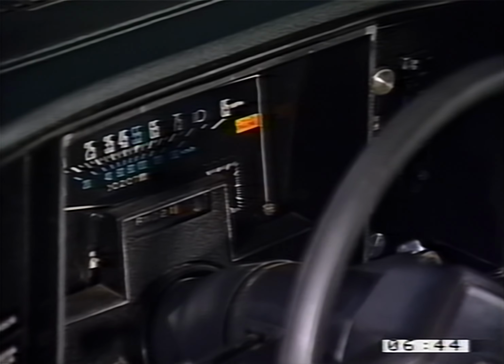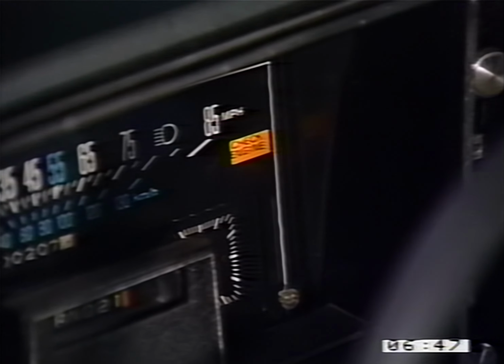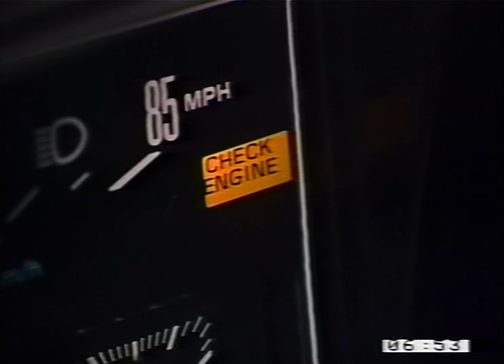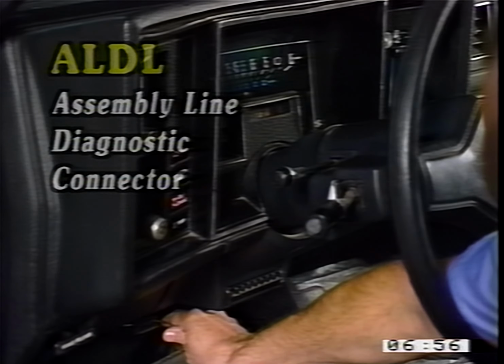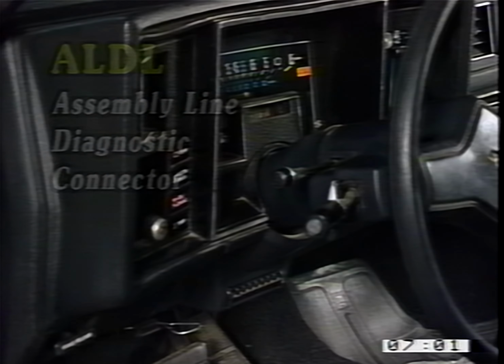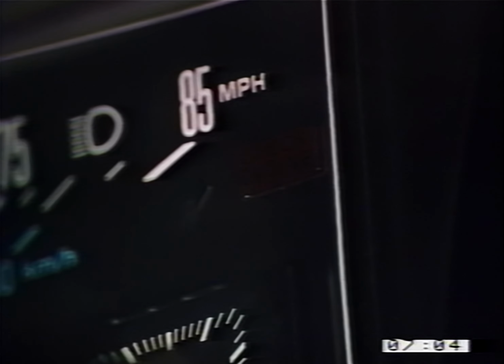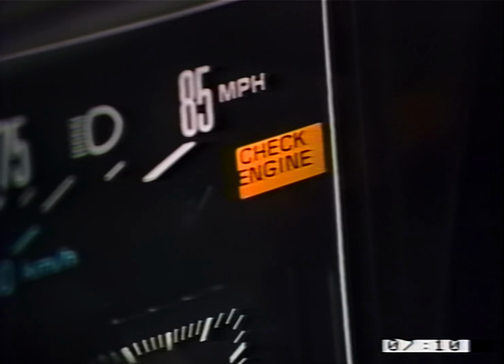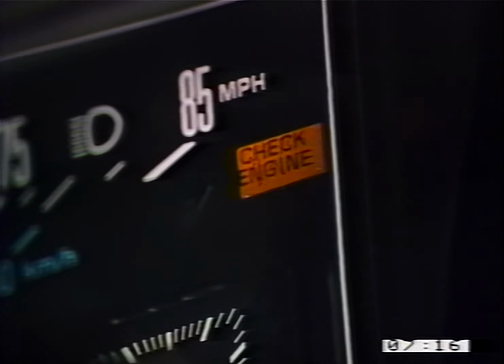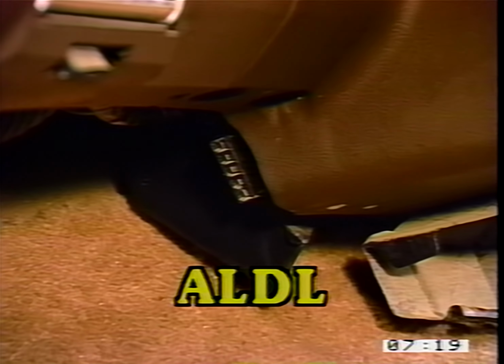The check engine lamp is one of the technician's primary diagnostic tools. The check engine lamp provides output from the ECM's extensive self-diagnosis application. A jumper wire plugged into the assembly line diagnostic connector, the ALDL, allows codes to be extracted on C3-equipped vehicles. A series of codes is stored in the ECM's short-term memory when there are problems in the system. These trouble codes can be recalled over a period of as many as 20 restarts, or until battery voltage is lost, whichever comes first. The ALDL connector is a block of 5 female spades set up in a common in-line connector, like that found in 80 and 81 models.